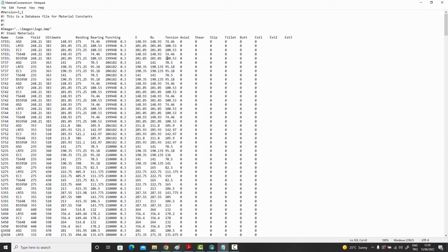You can lower, for example, the allowable bolt shear stresses, let's say 20-30% below the standard values taken. What that will help you with is that most of your initial preliminary designs will turn out to be green, right? But in any case, in the final analysis, once you actually create the report, you can see all the detailed checks done over there.